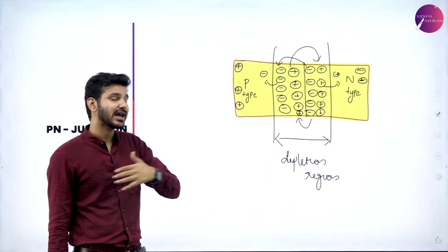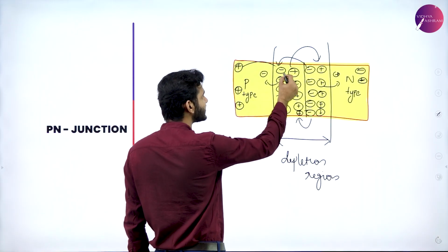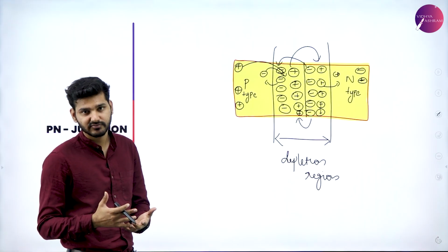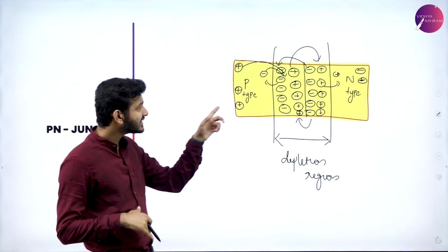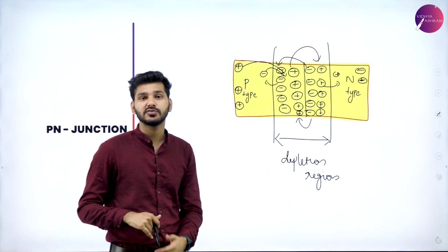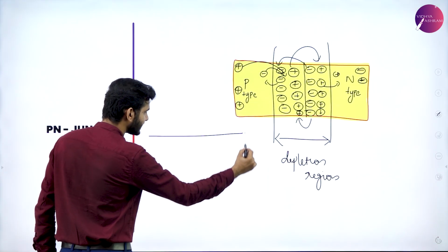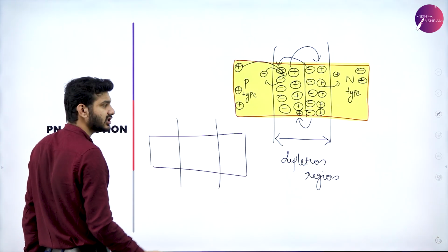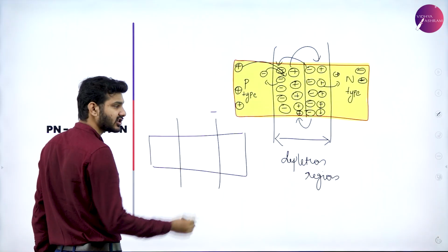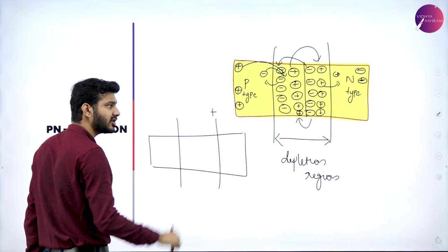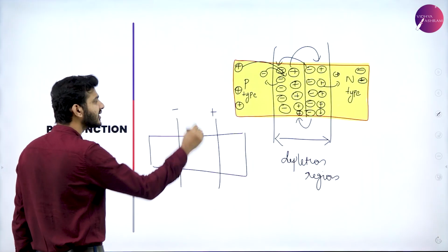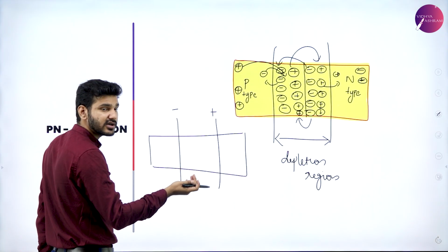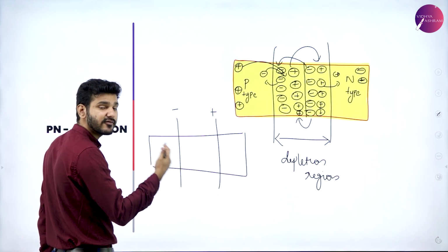But let's say that accidentally one positive charge or one negative charge entered into this particular potential barrier. Then what happens? Obviously, since there is a charge difference between these two, if this is a p-n junction and this is the depletion region, because of the potential barrier one side will be positively charged and the other side will be negatively charged. So this is preventing the movement of additional charges from entering from both sides.